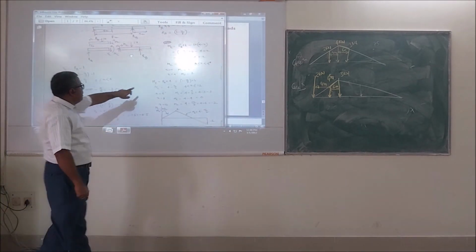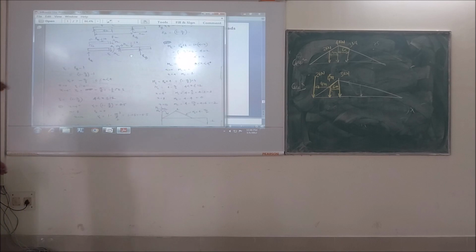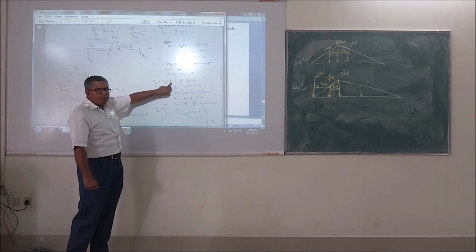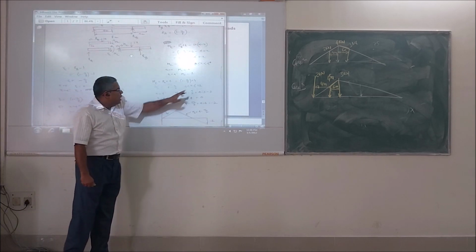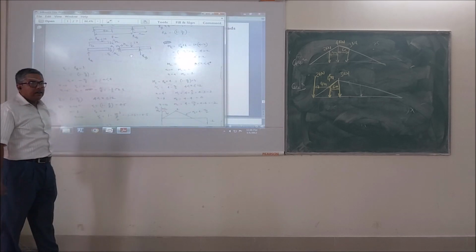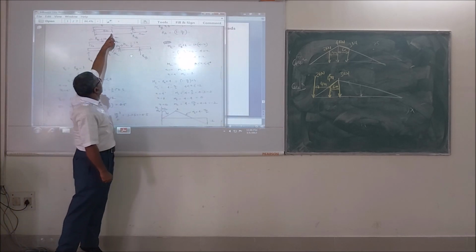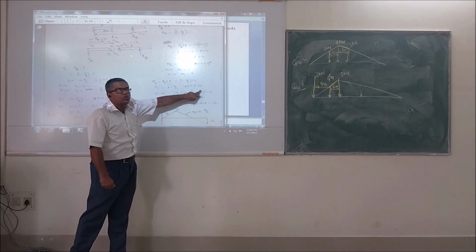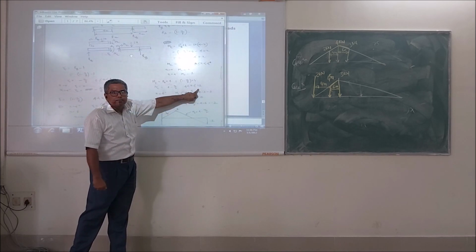I will get another condition, right? Exactly the same way, there is no difference. However, you see what we are doing? MC equal to RA into 4. So I do RA into 4, and where will this condition be valid? This condition is valid beyond x equal to 4, so x greater than 4, up to this value. Clear?